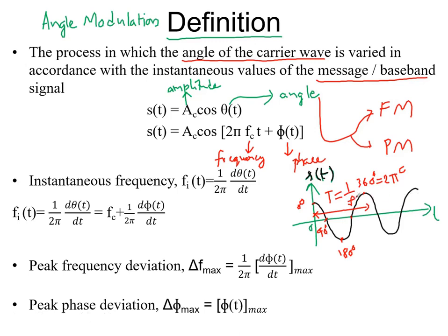Now here, how can you define the frequency? It means the phase is getting changed from 0 to 360 degrees, and the similar thing is getting repeated over a periodic signal. Only for periodic signals can you define the time period, for which you can define the frequency. That's why, how can you define your frequency here? It is defined as the rate of change of phase, and the phase is changing by 2 pi radian in one time period,